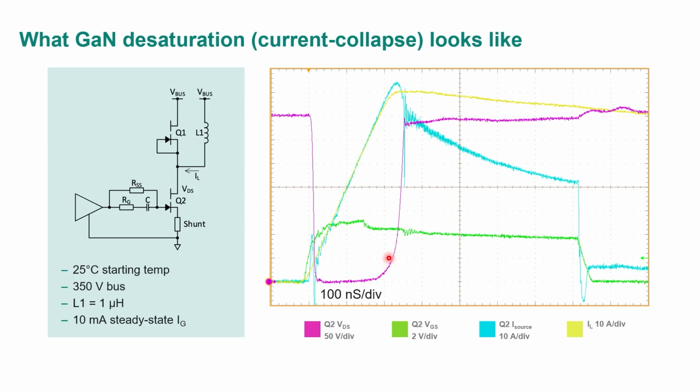And especially here, once I fully hit desaturation, this is just like an IGBT in desaturation, the same kind of mechanism occurs here, and the transistor can no longer support this level of current. And as a matter of fact, it even folds back.